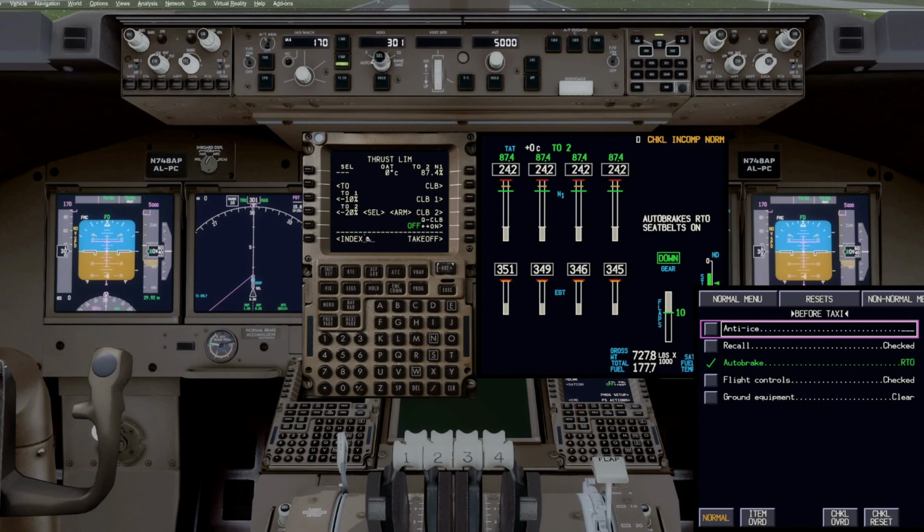One thing you should be aware of is that the max thrust reduction available is 25% less than full rated thrust. You can't reduce below 25%, so no matter what we do here, the thrust can only reduce a maximum of 25%.